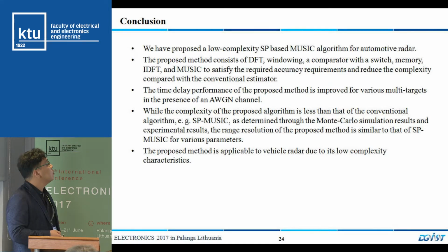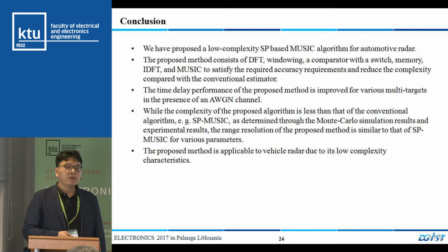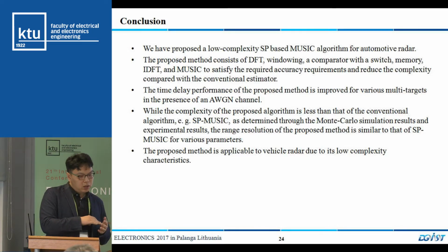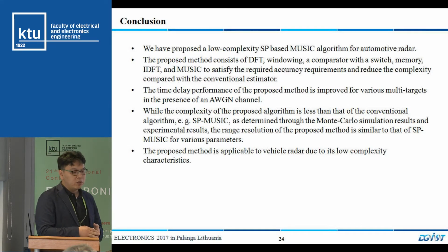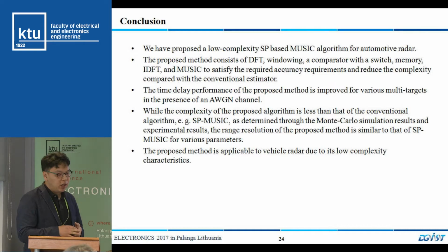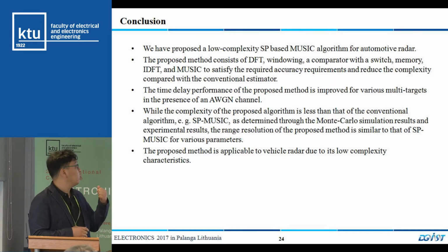We have a proposed low complexity spectrum partitioning MUSIC algorithm, and the proposed algorithm consists of the DFT, the comparator, the memory, inverse DFT, and the MUSIC algorithm to certify the required accuracy and reduce the complexity to embed in the automotive radar system.